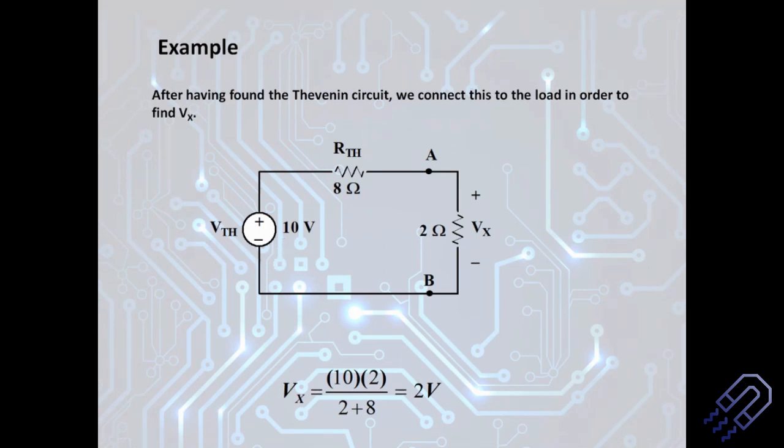Okay. So once we get this, we can actually have the Thevenin equivalent circuit. So this is called a Thevenin circuit. The previous one was not a Thevenin circuit. This is a Thevenin circuit because we have simplified the circuit and found the equivalent voltage and equivalent resistance. Once that's done, you can do any kind of calculation. Now you can have a 2 ohm here, a 10 ohm here, an 18 ohm here, but the calculation will remain very simple. But imagine the original circuit. Every time you have to find the equivalent resistance. Now you don't need to do it.